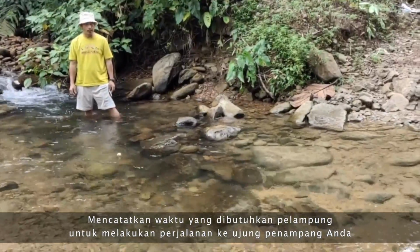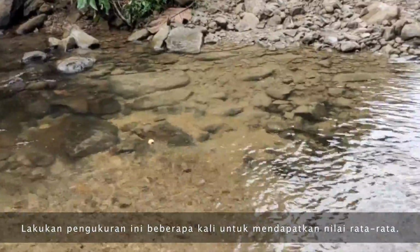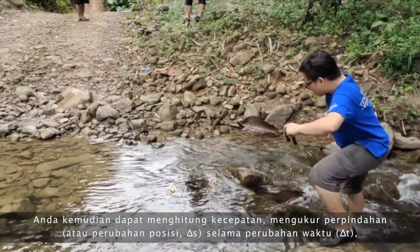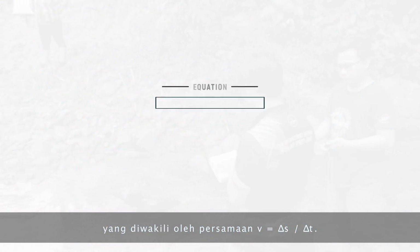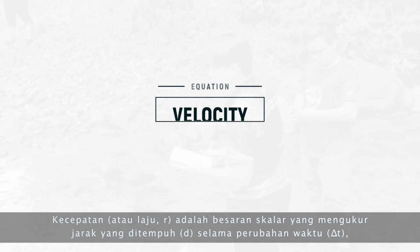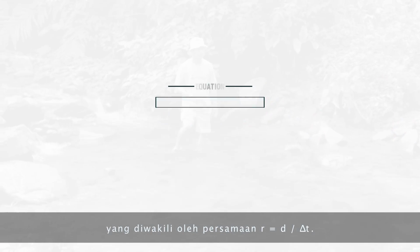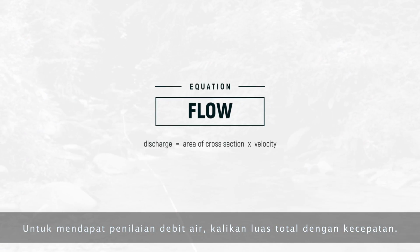The timekeeper takes note of the time it will take for the float to travel to the end of your cross-section. Again, take this measurement several times to obtain an average. You can then calculate the velocity, which measures the displacement or change in position over the change in time, represented by this equation. Speed, or rate, is a scalar quantity that measures the distance traveled over the change in time, represented by this equation. To calculate the flow, or discharge, multiply the area by the velocity.